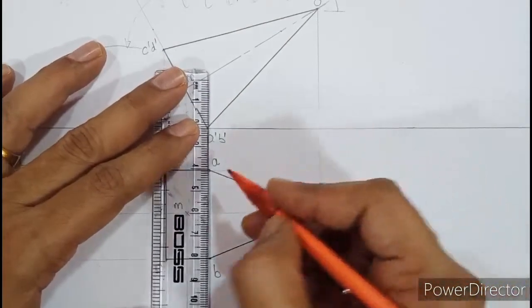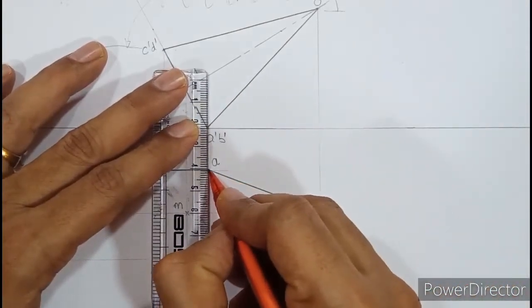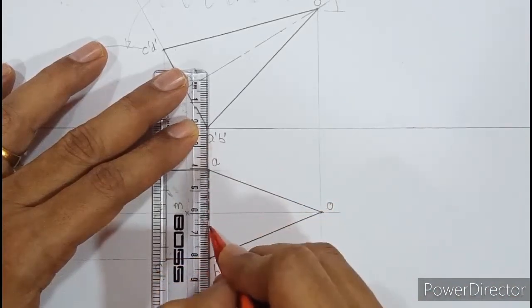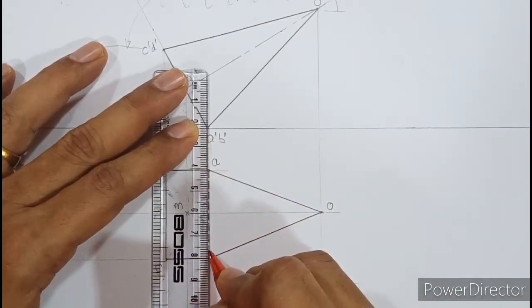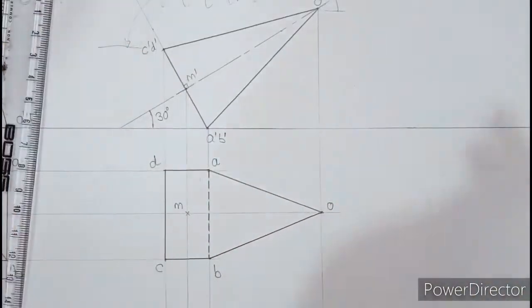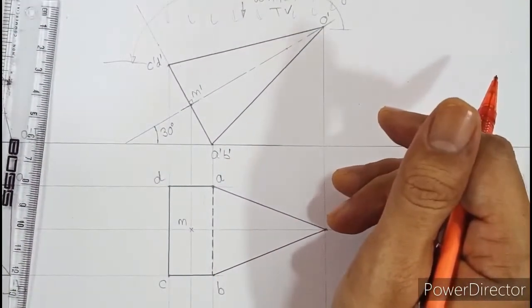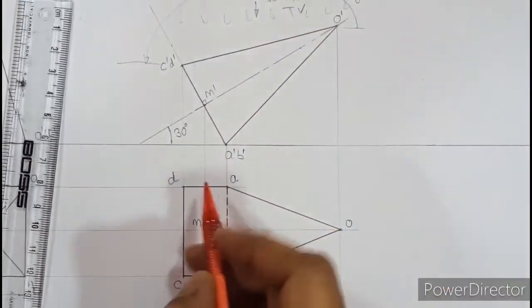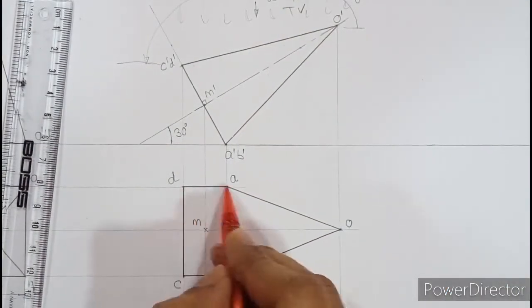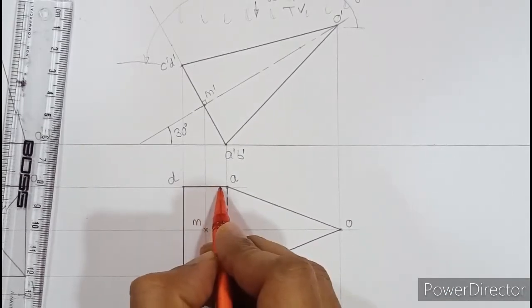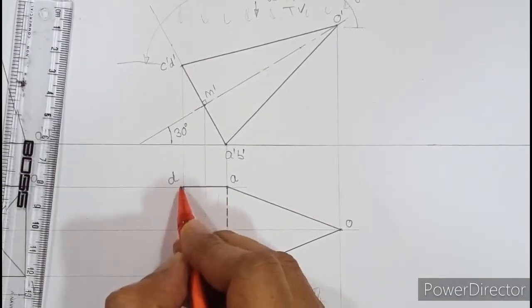So A to B, you need to double trace and draw a hidden line like this. Okay, so now that is not the end. The next step is you should carefully look at the base and find out which are the dark and dotted corners. When two dark edges of the base meet, it is called a dark corner.